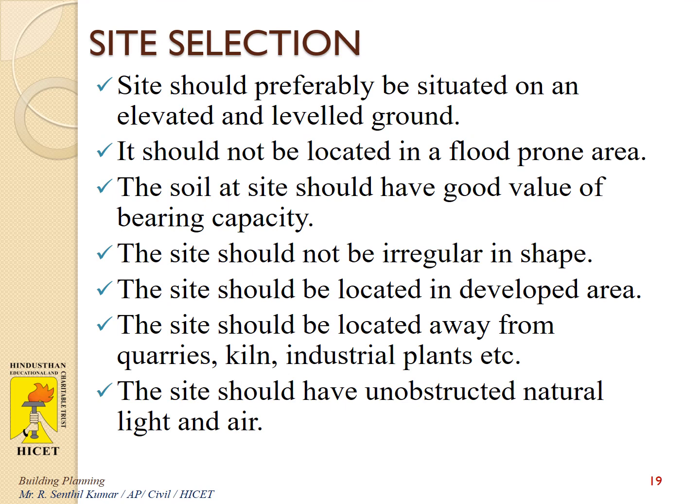And how to select the site for constructing a new house. The site should be situated on an elevated and leveled ground. It should not be located in a flood prone area. The soil at the site should have a good value of bearing capacity. The site should not be irregular in shape. The site should be located away from quarries or kilns or industrial plants, etc. The site should have unobstructed natural light and air.